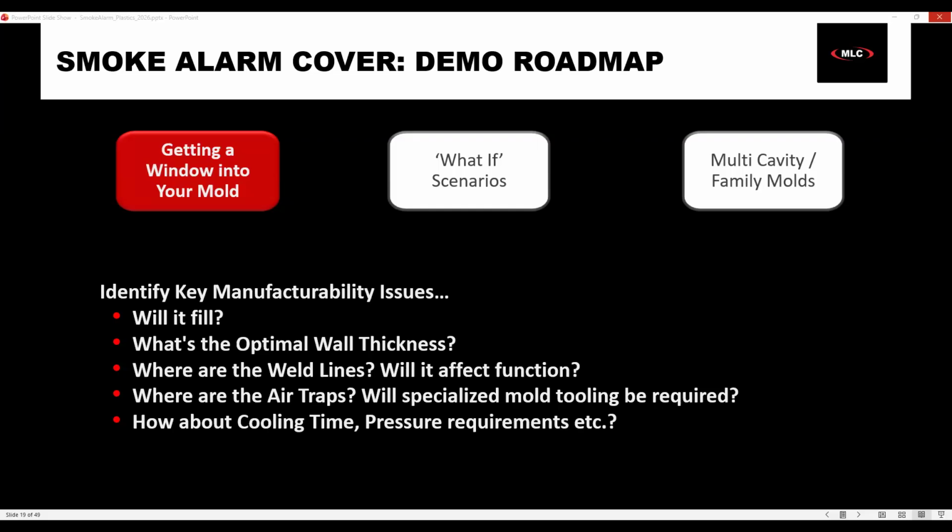In the tree, the next item is injection units. This is basically your material. One thing that I absolutely love about SolidWorks Plastics is that it comes with over 4,000 materials. As far as simulation packages go, it is by far the most inclusive materials-wise. These are all legitimate material properties for various types of plastics, not custom properties. You don't have to go download them. They come with the software.